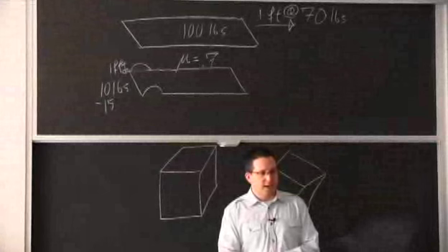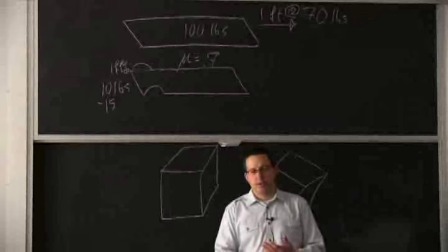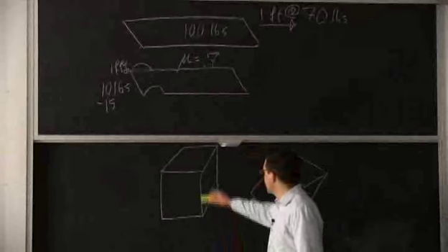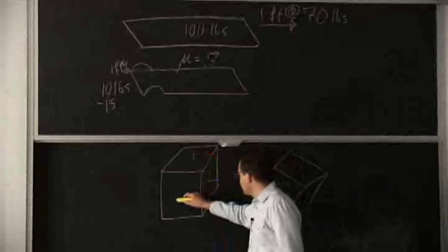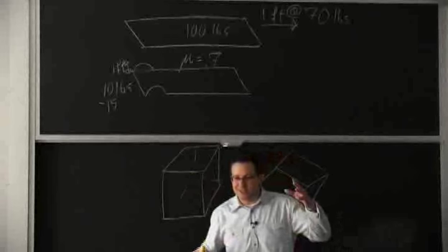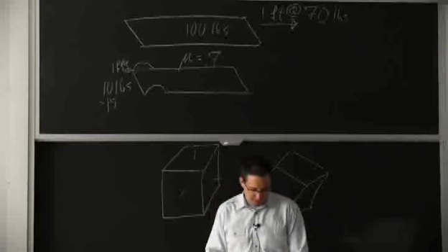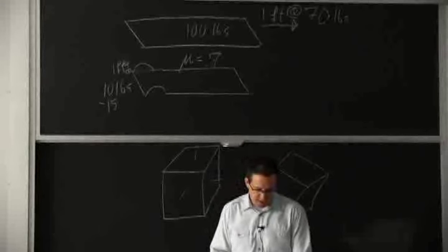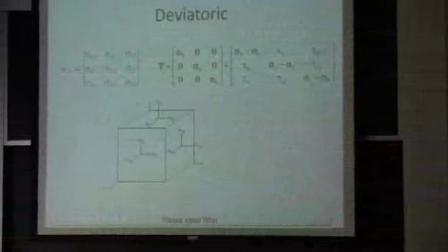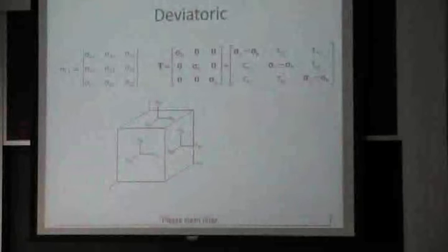So with the idea that when we have those principal stresses, if we take out the pressure, so the value of those forces here, normal forces, that are the same, what we're really left with now is what is changing the shape. And that's what we call the deviatoric, and that's on the right-hand side here. Now we still have some shear values here, but if we're working in the principal axis, they are 0. So we only have 3 components, and it's those 3 components that are going to change the shape when we deform.